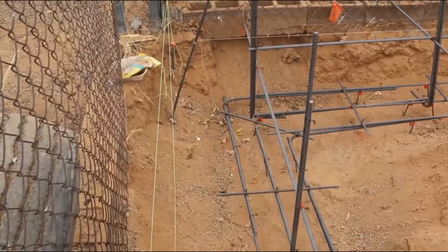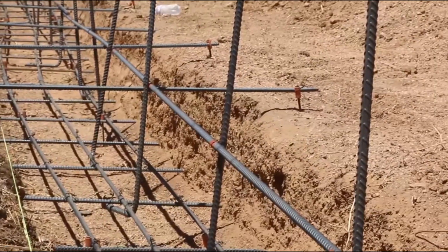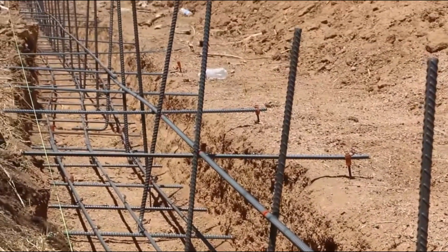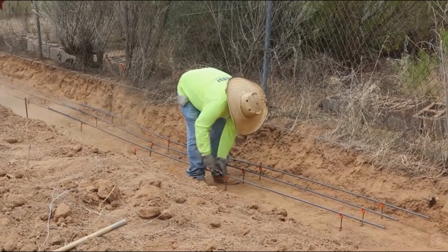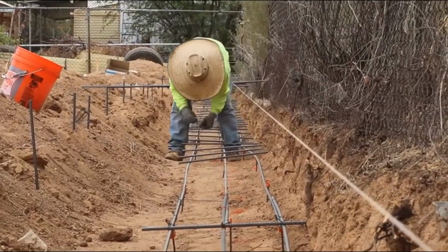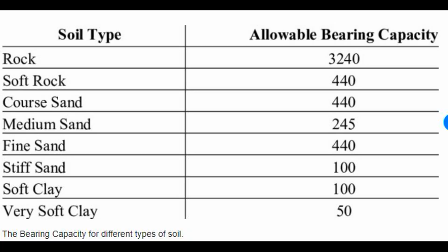Where you make a 90, where the direction of the wall changes, that's the only place that the system is braced. So in the middle of these long spans, the resistance to getting tipped over has to come from the footing, the width of the footing, the location of the wall on the footing, how far it's in the ground. So those are things the structural engineer is dealing with based on what the geotechnical engineer told him, to make a wall system that is always going to look as good as it looks when it's new. Okay, here I would like to comment about soil bearing capacity and loading for a masonry block wall.